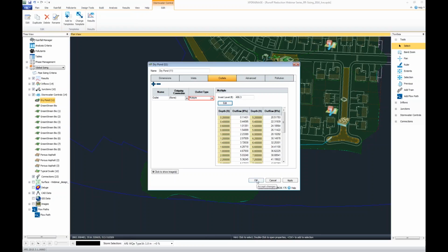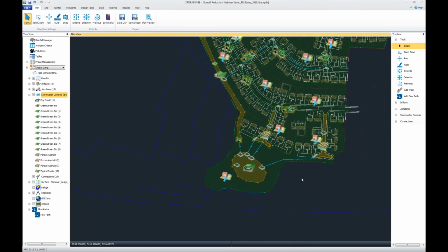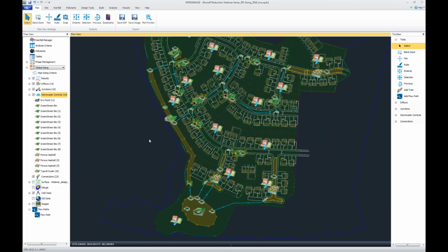But this, I guess, is kind of the bookend for today that I wanted to show. So we talked about not only the outlets at the end, but also, we looked at just briefly the different types of rainfall. Usually it's going to be something along the lines of a HUF or an SCS, most commonly in the U.S. Right? We can accommodate a range of different rainfall formats, obviously solve these different events with these different designs, and begin to size either individually or globally our system.